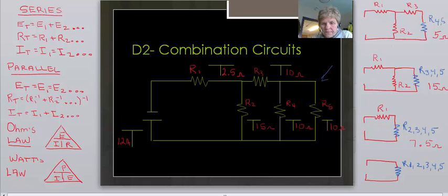When you look at this circuit, R1 is now clearly in series with the equivalent resistor for all of these guys, 2, 3, 4, 5, and I use series circuit rules to add them together, and I'll get 10 ohms as my total resistance. Then I could take that 10 ohms over here to my supply T, which shows all my totals, so there was 12 amps total, 10 ohms total. That will give me 10 times 12 is 120 volts, and I know that's my source. Coming out of the negative will be my total current, and that is 12 amps in this case.